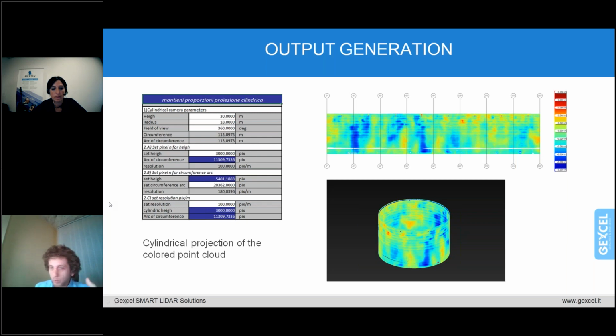These orthophotos, you can then export nearly with one click back into AutoCAD. So Reconstructor offers a possibility not just to export a plain JPEG or PNG file, but with an AutoCAD script exported together with the image file, you can just drag and drop it within the DWG, and you have your orthophoto properly positioned and scaled.